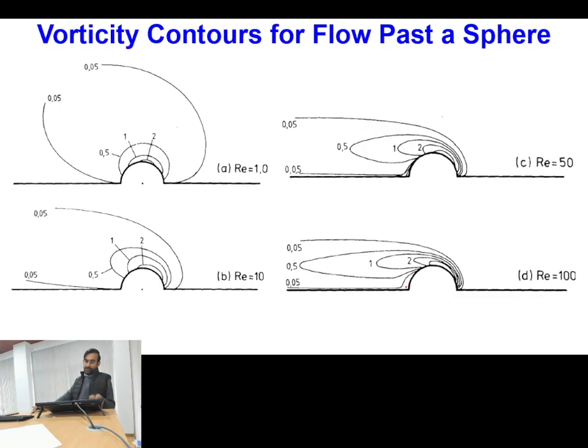And in terms of the vorticity field also you can see, this is the contour of the vorticity field. In case of low Reynolds number, your vorticity field, though it is convecting towards the downstream direction, is still coming closer to a symmetric field. Whereas in the cases where Reynolds numbers are significantly high, you have faster convection of the vorticity field towards the downstream direction. Okay.